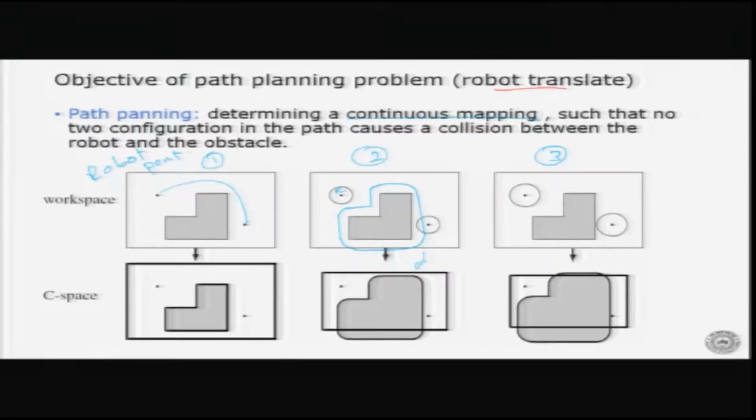Now, it is very clear that at the bottom side there is no free space, which means the robot cannot go in that direction. So, if it has to go from here to here, it can go only this way, there is no other way. Now, in the third case, the robot is a slightly bigger size, and we again draw the C space obstacle. So, we draw it like C space obstacle is going outside now. So, like this, the robot is much bigger in size.